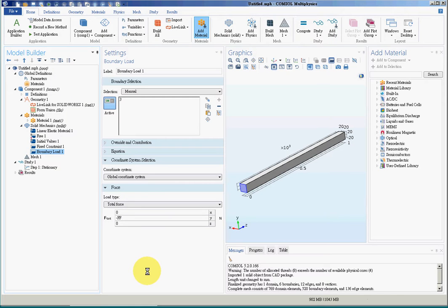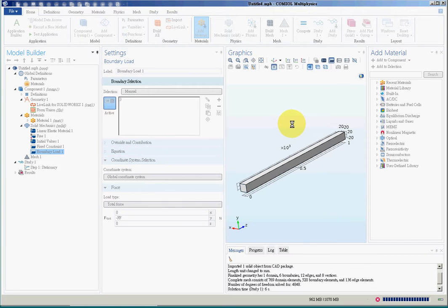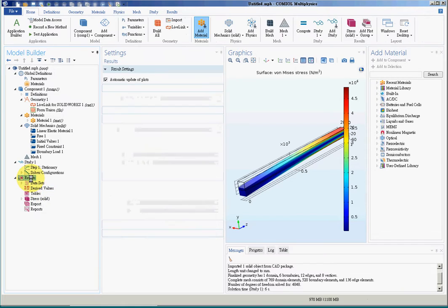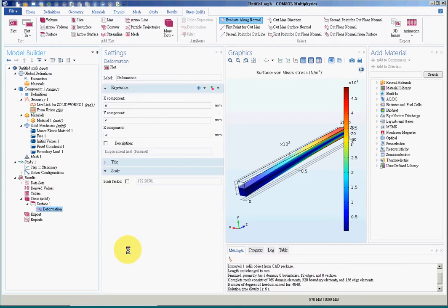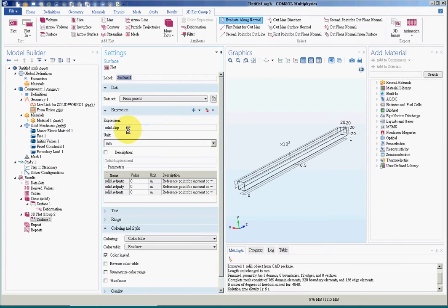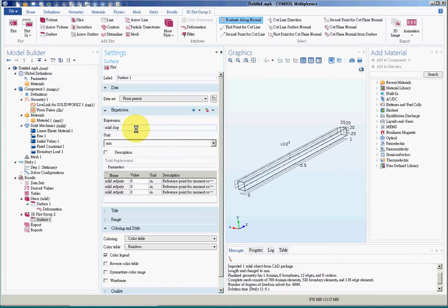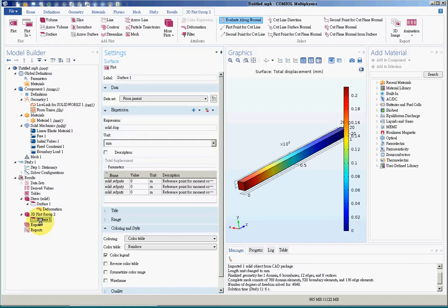So I finish with preprocessing and I'll calculate. And this is step 5. And after finishing calculating, we'll enter step 6, which is the result part. The software displays stress, and we'll add another 3D plot and add a surface plot of displacement. You can change items into others like stress, strain, or other displacements. And I'll accept the default displacement plot, and I'll make it deformed.